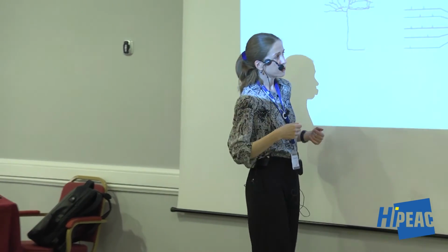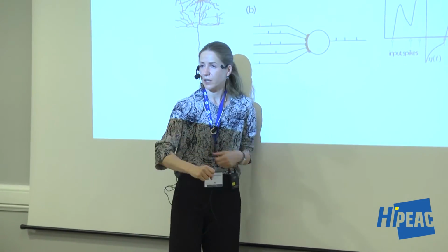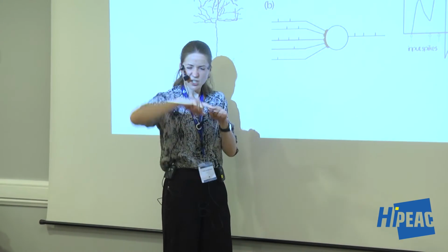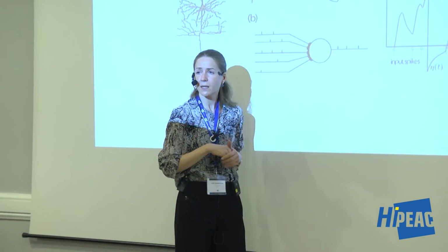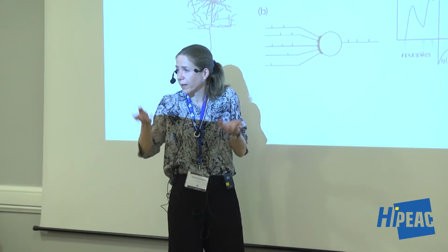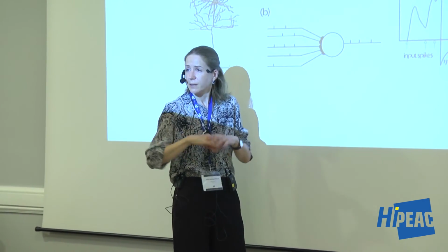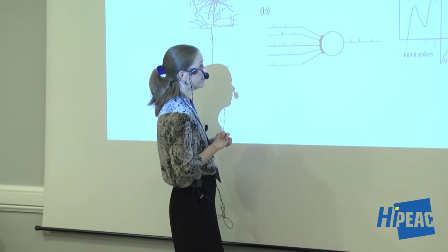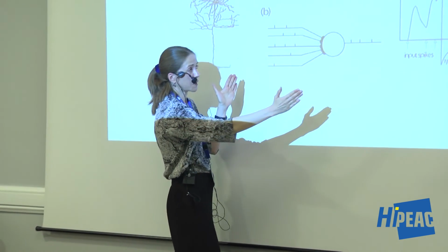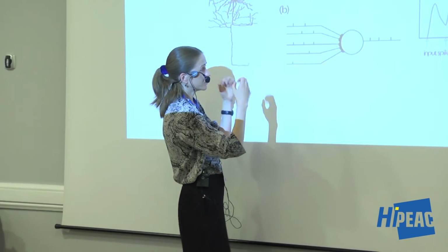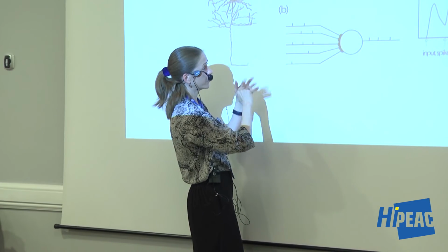I can imagine they had long debates about how to communicate the spike, what to do there. So what they decided to do is to do this spike communication digitally. Because they postulate the shape of the spike doesn't matter. Only the fact that there was a spike matters, and that we can encode in a normal binary digital way. It will be simpler, and then we can build systems that we can scale. So this is a simplified neuron with the level of abstraction that neuromorphic computing people have now adopted.